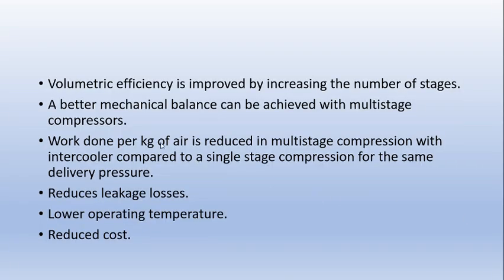And the fourth one, reduced leakage losses, because the pressure handled by each cylinder will be less compared to a single cylinder. So the possibility of leakage losses will be less in a multi-stage compressor. Lower operating temperature.